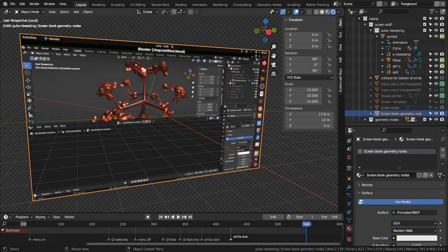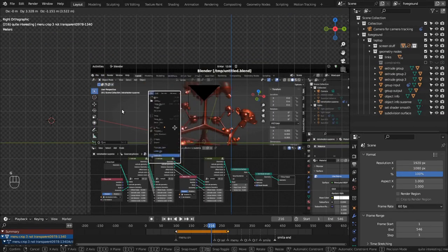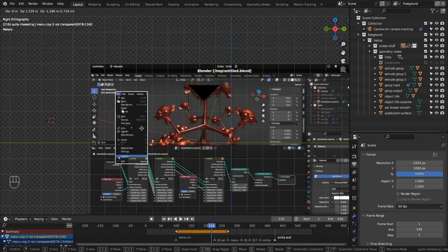This is the screen backdrop at World Origin 0,0,0 and is scaled up 10 times to 18 by 10 meters, as I have found problems with rigid body world simulations when objects are too small. When positioning screen objects in their starting positions, I use the orthographic right view, so as not to bugger up the x coordinates of the various image planes. Bugger up is a technical Yorkshire term.